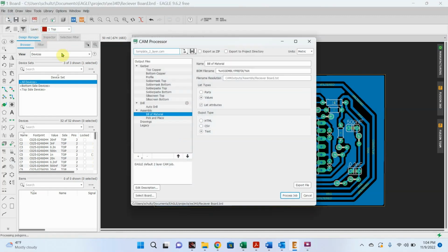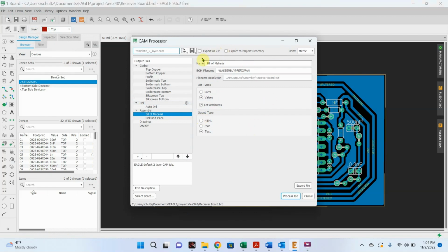Yeah, that's just asking if the design was changed. So now what we need to do first is get the correct CAM file. To do that, you come up here, load job file, and then you'll see this drop-down window. A few different options. We want to do an open CAM file.